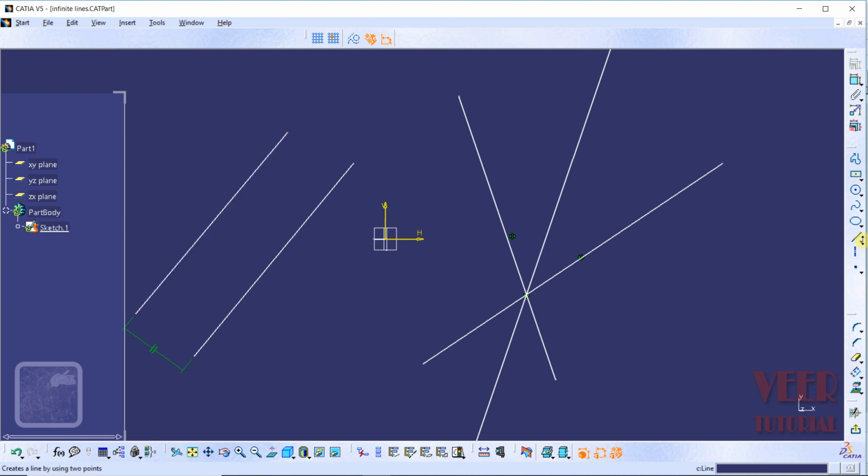And then I go to the line option, I select this bisecting line. So now we need to select the two lines. So this is the first line and this is the second line. And now we can see we have a third line that is at an equal distance. So this line is created at the equal midpoint. So that is why it is called a bisecting line.